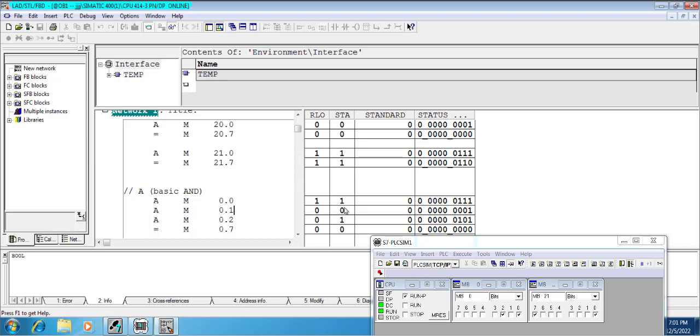So the first instruction, as we said, comes, checks, sees that the first check bit was 0 and the OR bit was 0, deduces that it has to move the current value stored in the address to the RLO, and therefore the RLO after this instruction becomes 1.